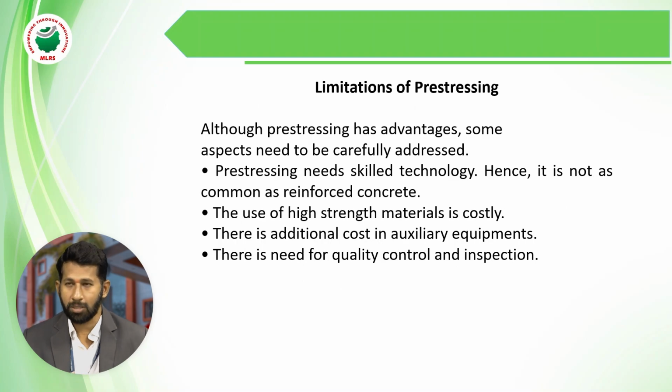So what are the limitations of prestressing? Although prestressing has advantages, some aspects need to be carefully addressed. Prestressing is a skilled technology, hence it is not as common as reinforced concrete. It uses high strength material which is costly, there is additional cost for auxiliary equipment, and there is need for quality control and inspection. So these are the limitations of prestressed concrete.